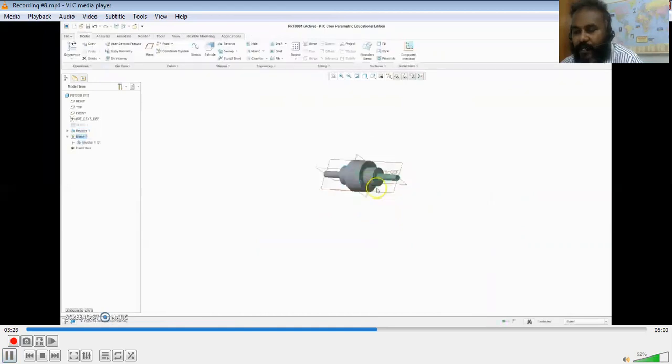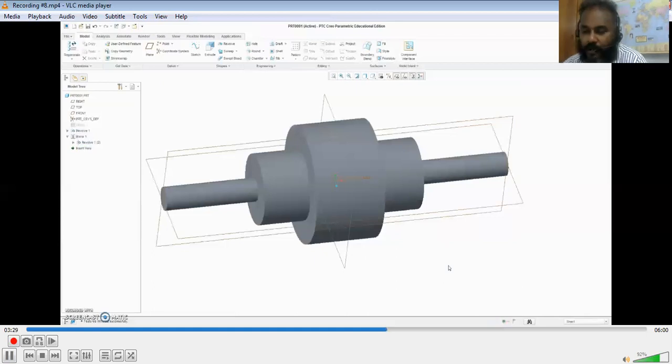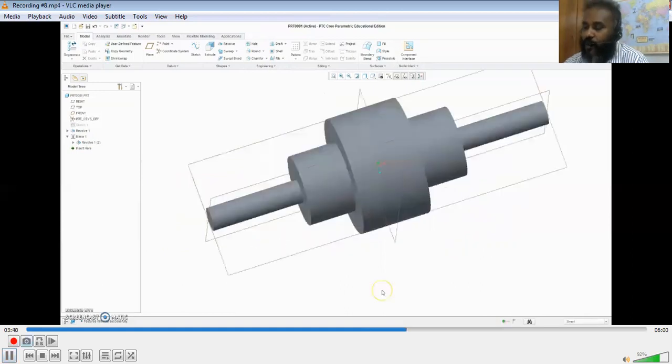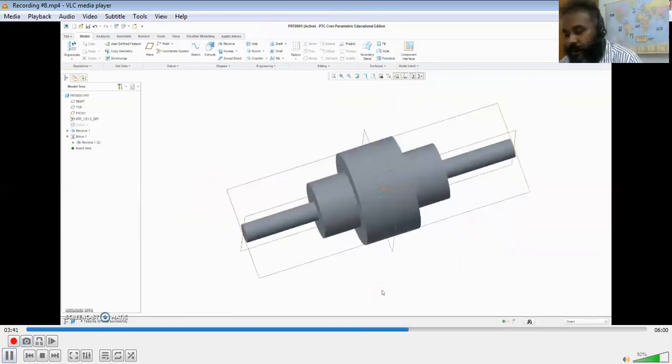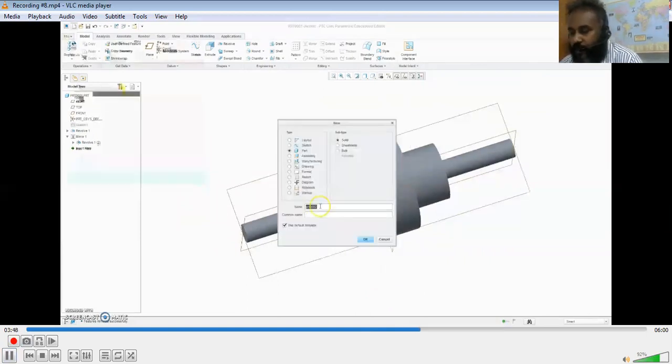So click that, and what plane you want to use as datum. I chose the face of the extruded part. What is it? Rotated base. So once that was chosen, it got mirrored. So this way we got the final object of desire, say, through the revolve option. So this is one way of doing it. There are many other ways in which you can do.